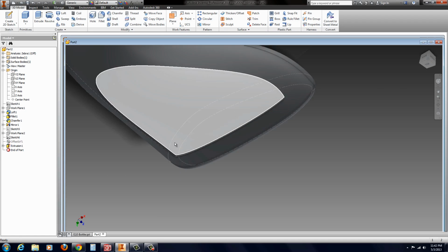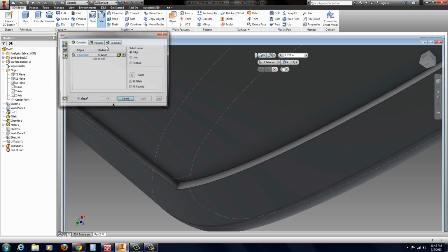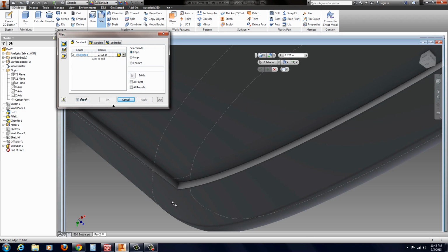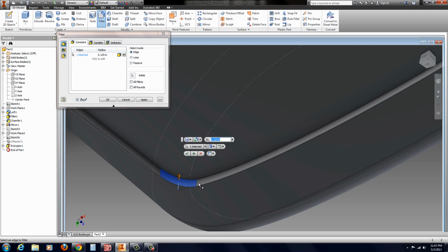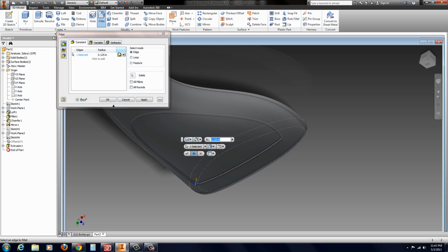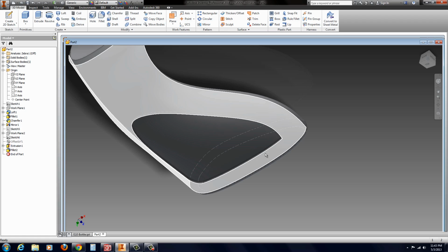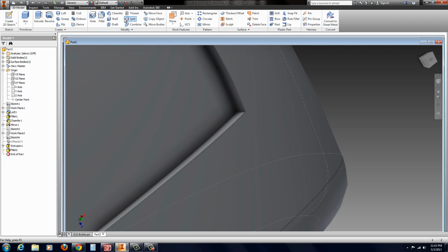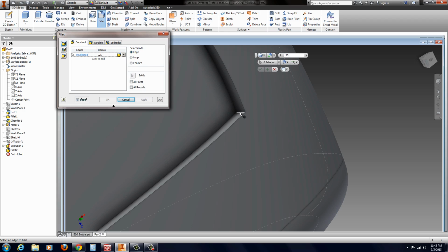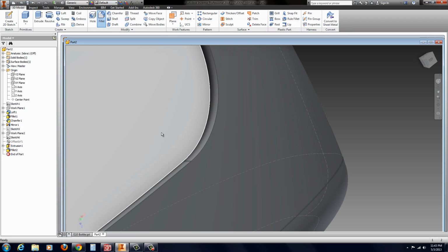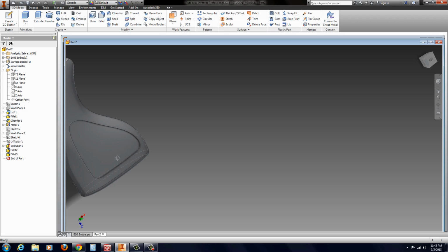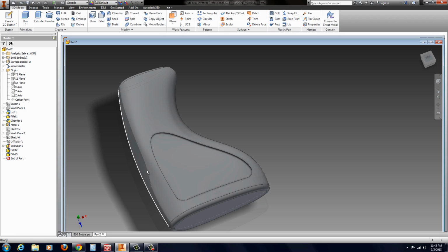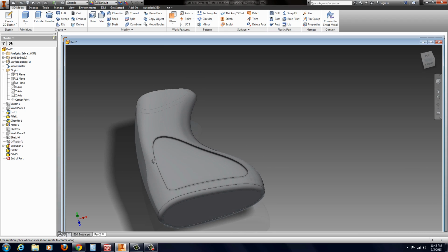And now go ahead and put some fillets or rounds in here. And again, you could use the curvature continuous if you prefer. I'm just going to put standard 0.25 over in this corner. Unfortunately, I was not able to get the sketch fillet to work on that. It doesn't seem to like the spline, so that's why I'm doing it right now.